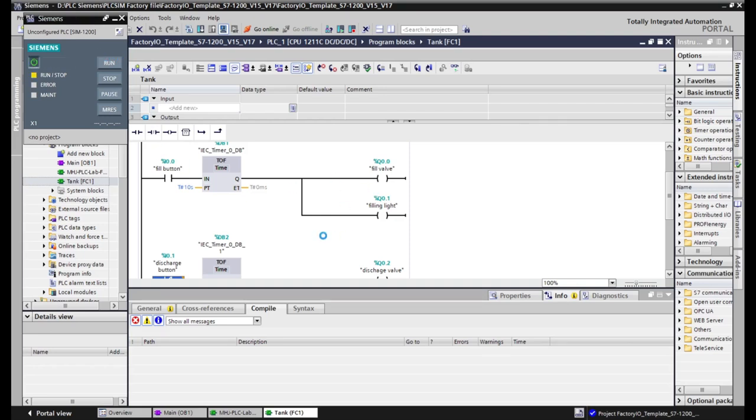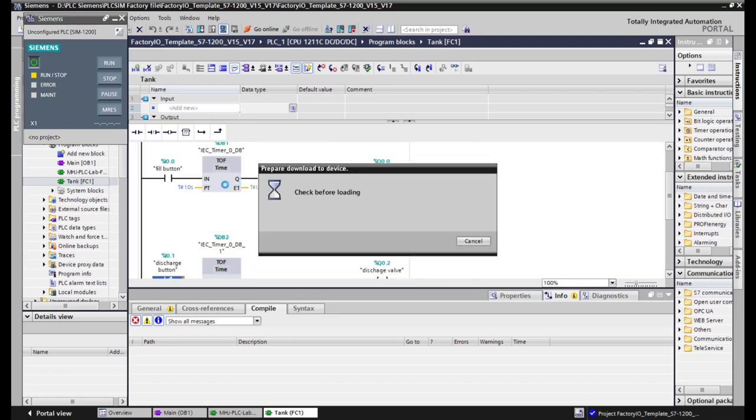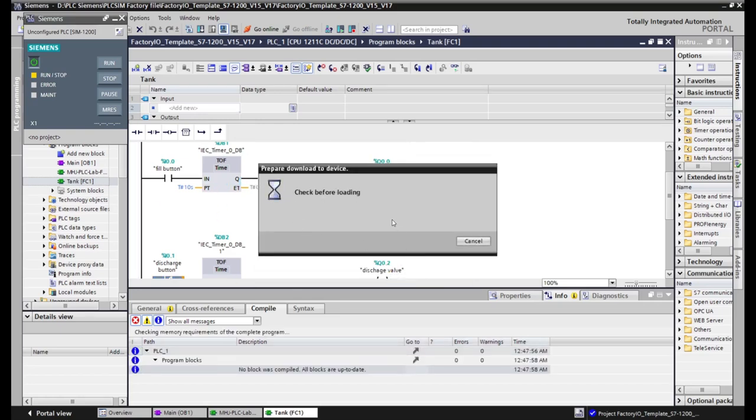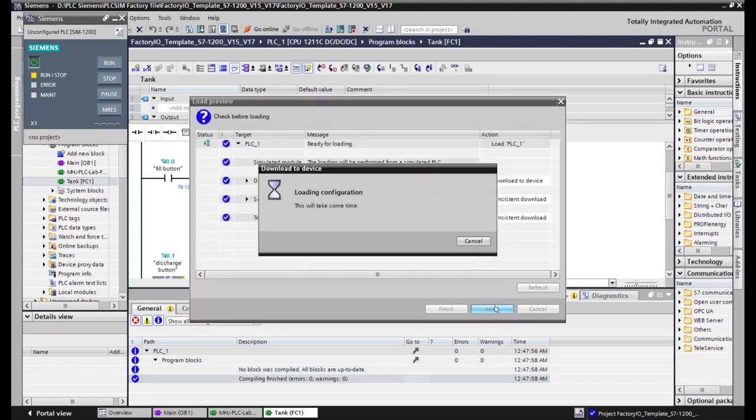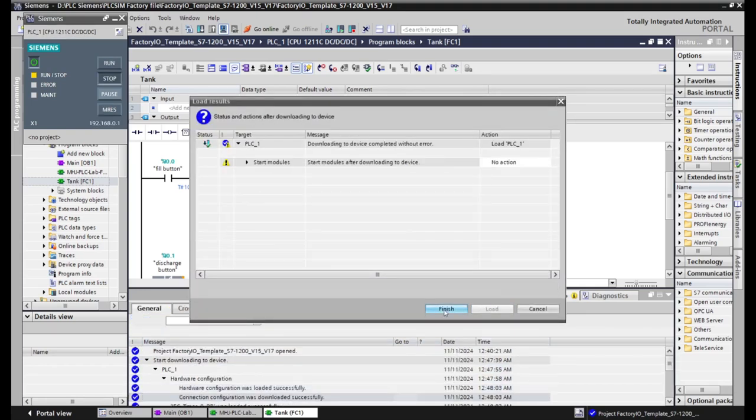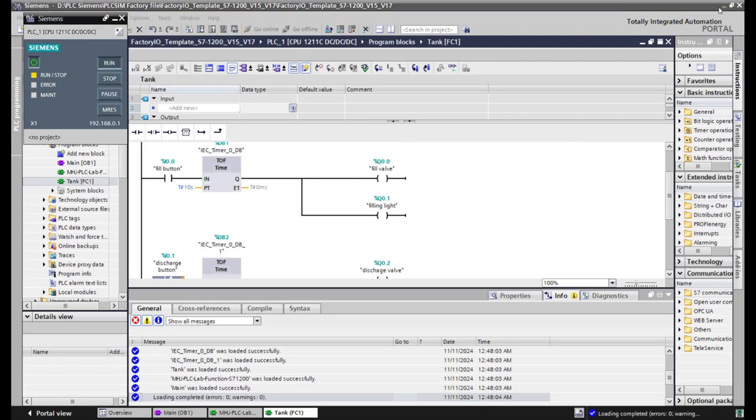So I'm going to upload it to the PLCSIM, and after the program detects it, it is going to show me a window where we're going to accept all the terms and all the trusted devices just to load the code into the virtual PLC. And after that, we're going to connect it with Factory I/O. So I'm going to load this little program into the virtual PLC. We just need to wait a little. Yes, we need to load, and I'm going to run.